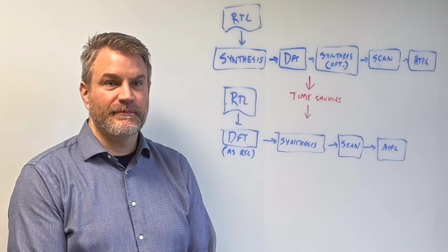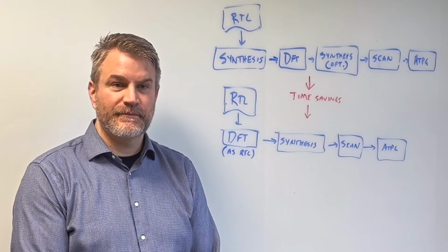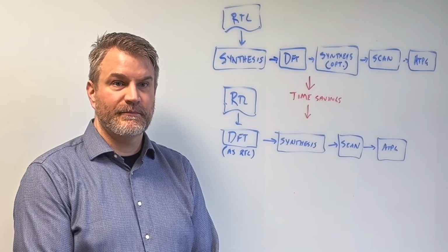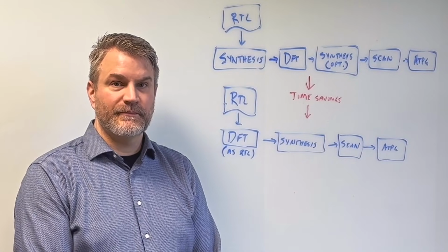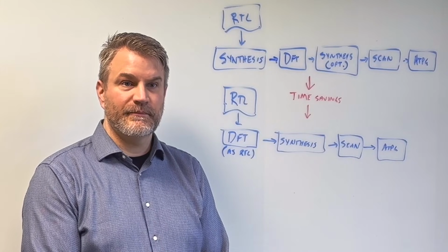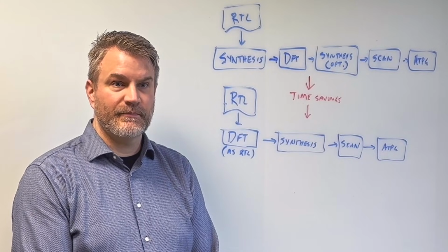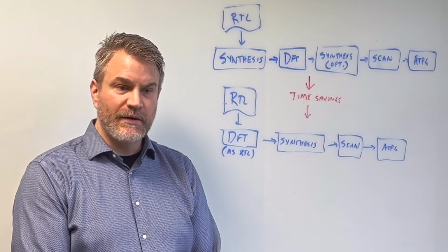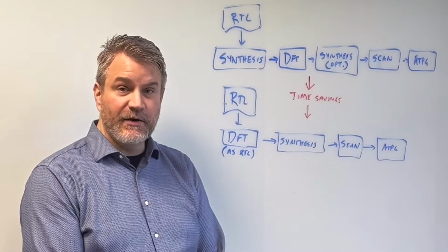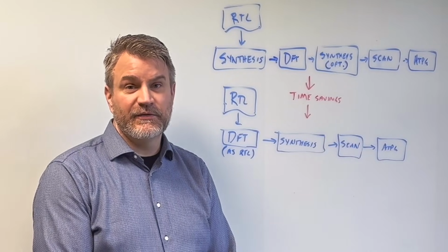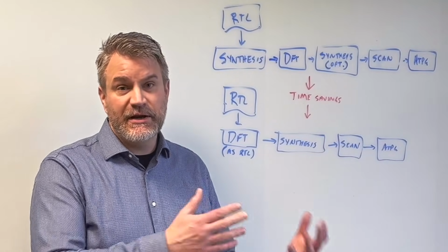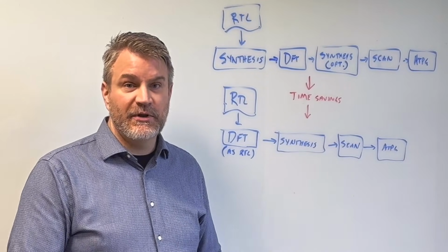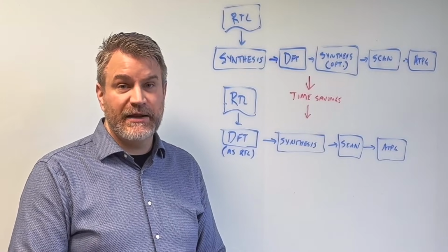As the chips become more complicated, as they become denser, as they get more different pieces and go up into the axis, you now have a lot more RTL that needs to be gone through in order to design whatever you're doing and test. What are you running into in terms of problems there, and how do you manage it? I mean, you've got complete change here that didn't really exist a couple nodes ago. Right. And with that RTL complexity analysis, DFT engineers on a project can provide meaningful feedback to the designers to help clean up their RTL and make it both manageable and testable.